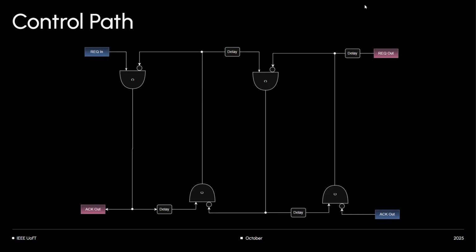What happens? A 1 goes through. Where does the 1 go through? First of all, it comes out on the acknowledge, right? You will get an acknowledge here. That 1 will go through here. This is just a delay, for timing. I'll explain what this delay is for in a bit. You'll have the 1 come through here.